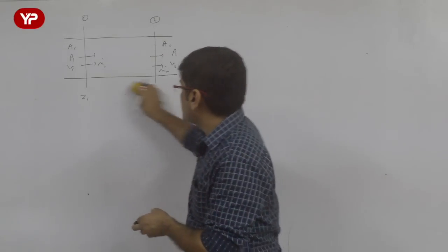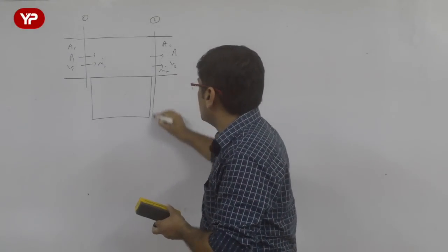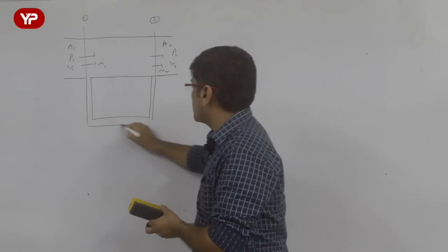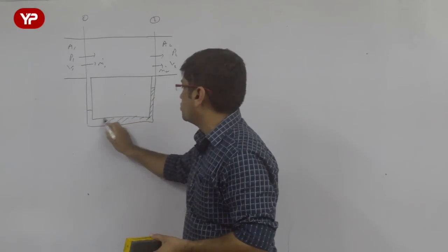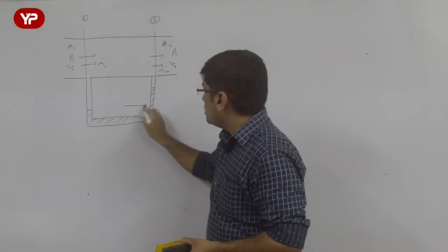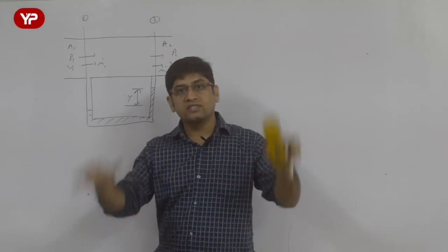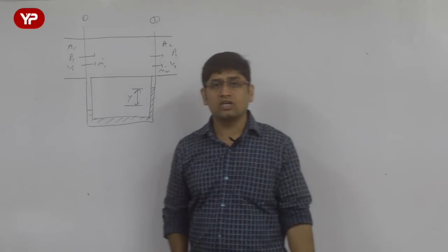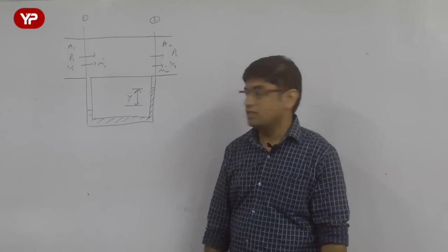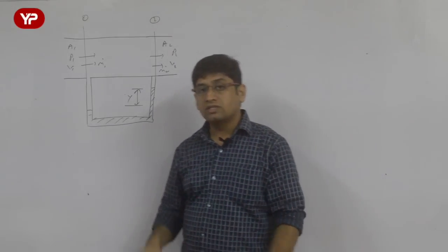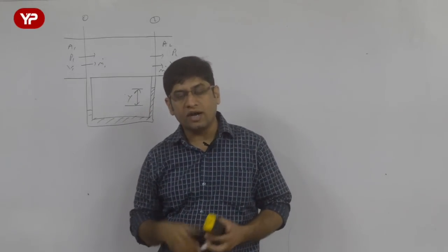And moreover, he is going to tell you that suppose I connect a manometer here. You know, a manometer is the device which measures the pressure at two different sections. Suppose I connect a manometer in which mercury is kept like this, then the two limbs of the manometer show some difference. Mercury is not at the same level. There is a level difference in the two limbs. Why is this level difference coming? That is the question he is going to ask you. That means certainly pressure P1 is more than P2, but Bernoulli equation is not going to give you that. Why is it not there?